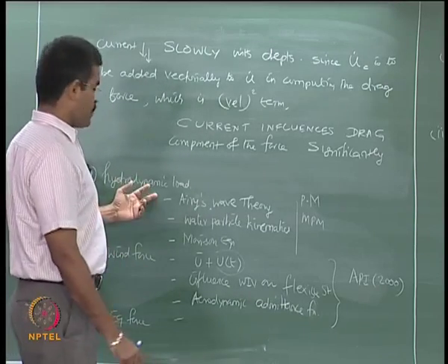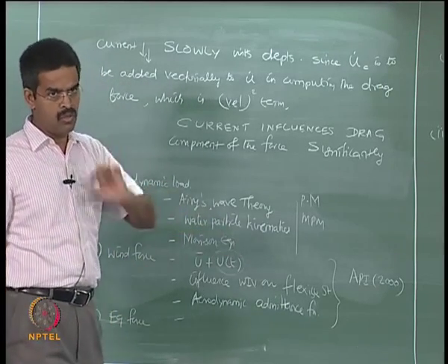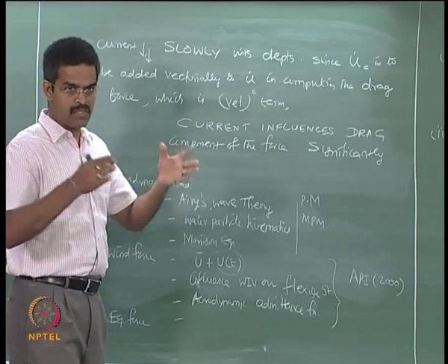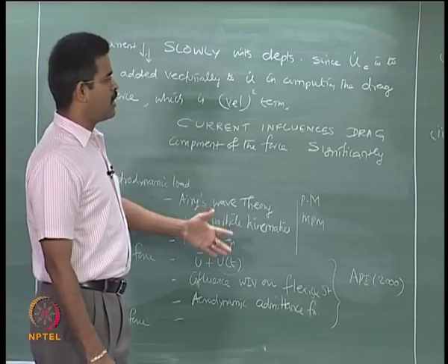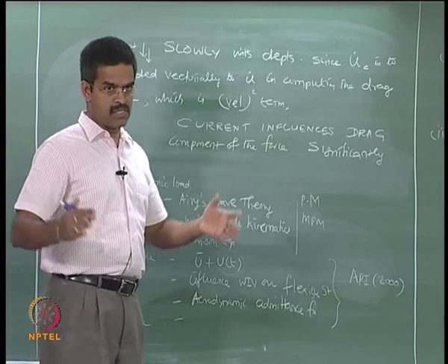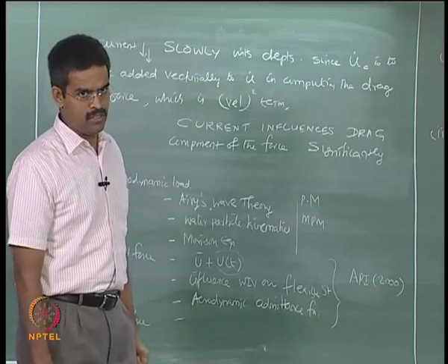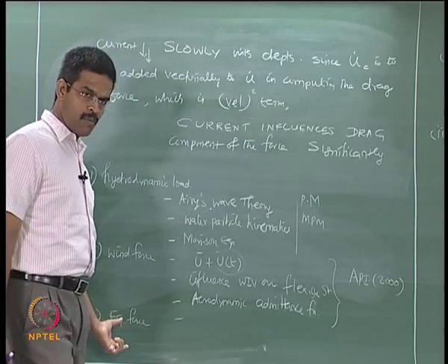In addition, wave induces an inertia component also, whereas earthquake force induces only the inertia component. So, the mass of the structure is very important, and offshore structures are very large in size and very heavy in mass or weight. Therefore, inertia forces become predominant.